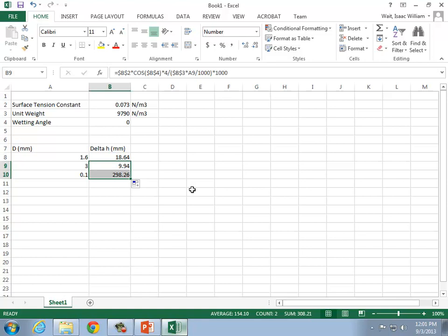Above the water table, there can be these long routes that water will rise up through, because just by statistical probability, some of the pathways are going to have connected really small voids. There may be some routes where just by circumstance there would be a big grain on top of another big grain on top of another big grain, so the voids around them would be large. But one interesting application of surface tension is that it can cause something called capillary rise in soils, and so it keeps the soil moist even above the water table.